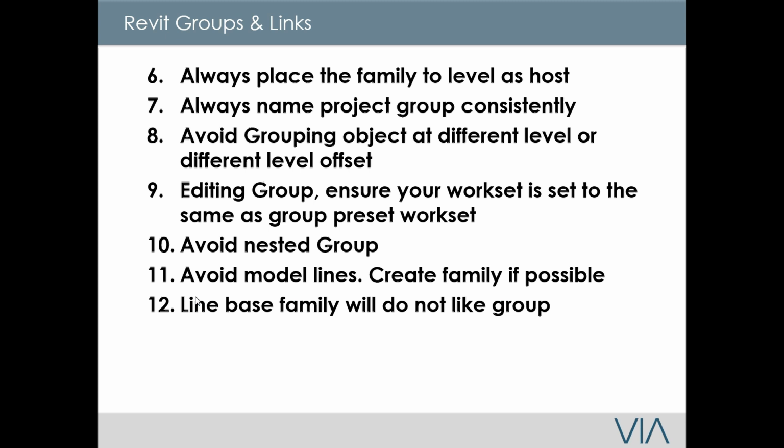All right, number 6: always place the family to the level as host. What I mean by this is that whenever you insert furniture or any appliances or any Revit families, I always recommend that when you put it on a floor plan, place it on the level and not onto the floor slabs. What happens is that when you do that and when you group it, it wants to break away from the group.